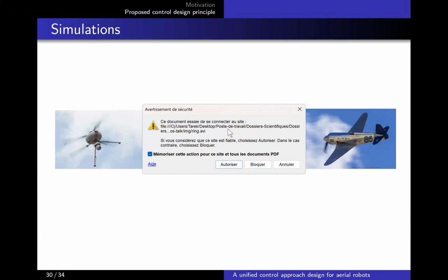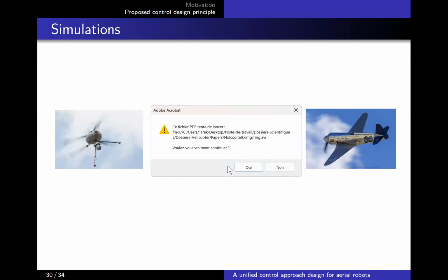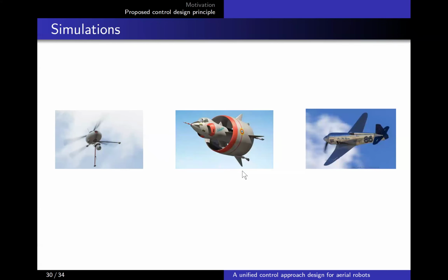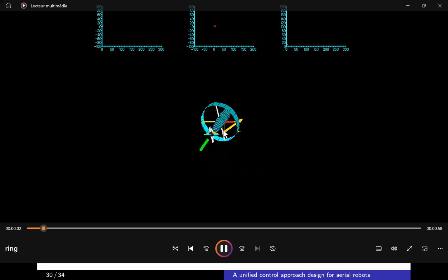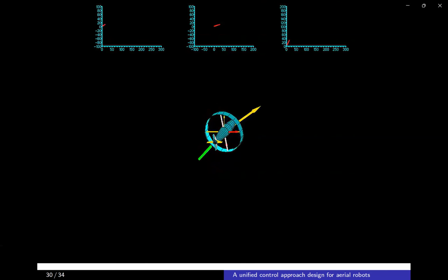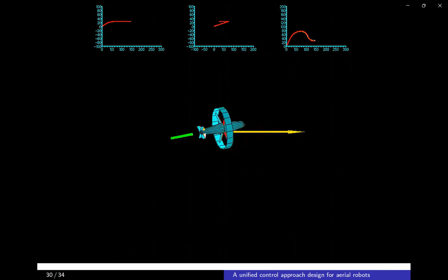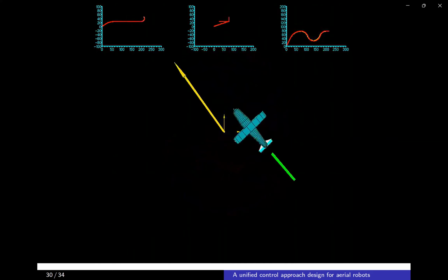Now, the same trajectory with the annular wing, which is axis symmetric, like the missile. We added just an annular wing in order to have more lift, okay? And we see the thrust here is lower than in the previous case, okay? Because we have some lift which is helpful. Not at the end, because at the end when you stabilize, we have to compensate for the gravity. But you see at least the trajectory, how it works.